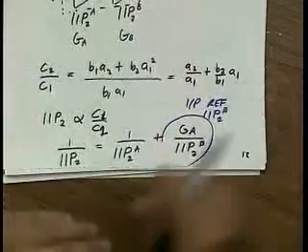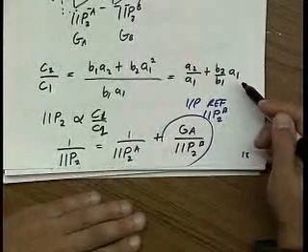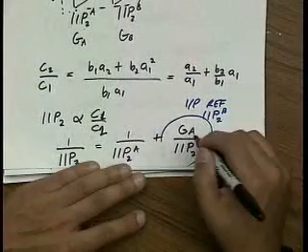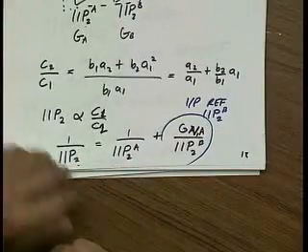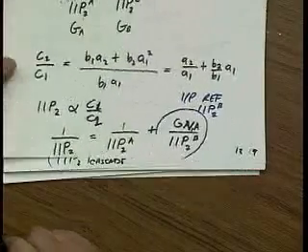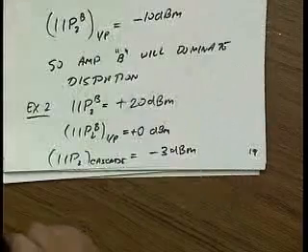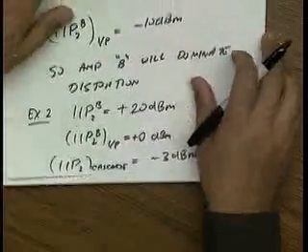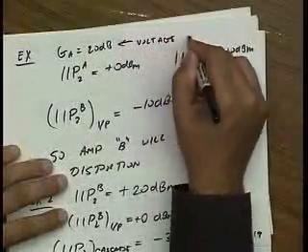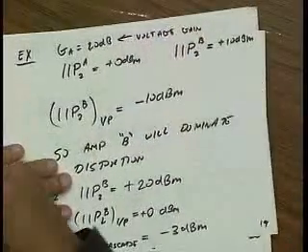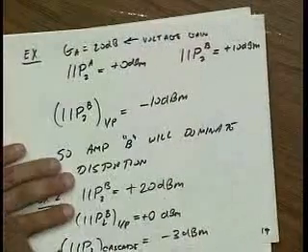So here, A1 is not the power gain, right? A1 is the voltage gain. So this should be GVA, the voltage gain of amplifier A. And so in the example, this is the voltage gain. Well, if I give it in dB, it's automatically taken care of.